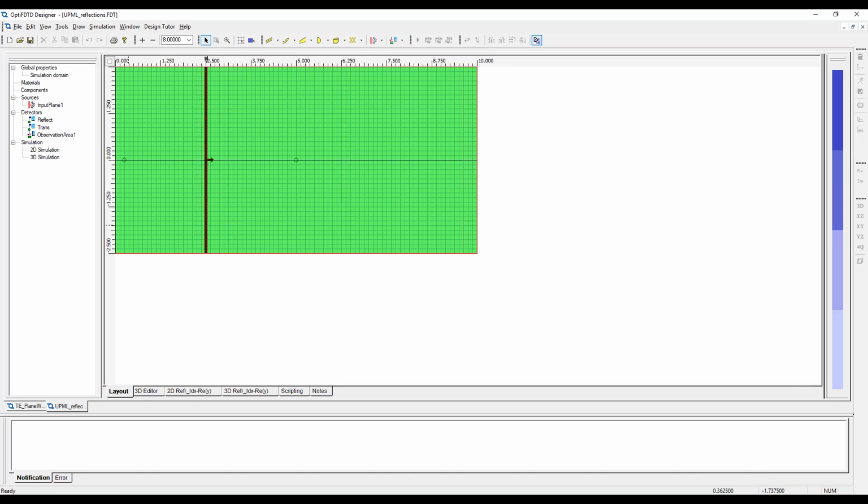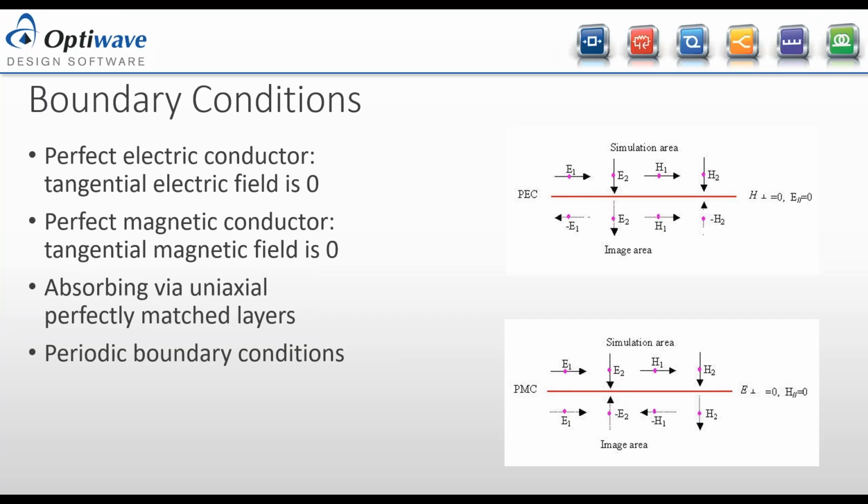All right, so let's go back to we just showed that absorbing boundary condition there. And now let's return to the slide because I haven't really explained how these observation objects work. I've shown the observation point, which is fairly simple to understand, I think, but I haven't explained the more used observation type object, which is the observation area, and how that works.